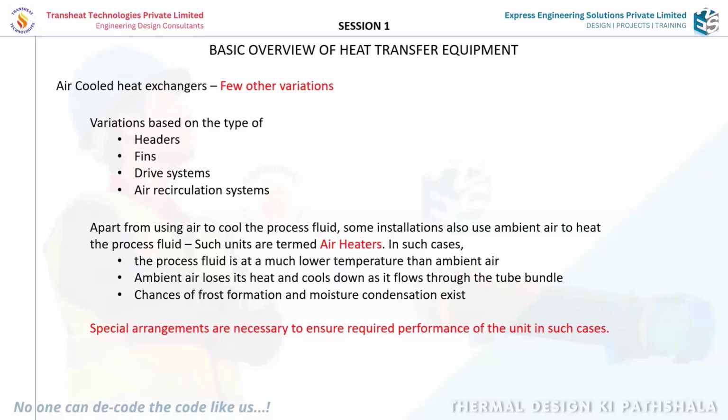So the chances of moisture condensation and frost formation on the finned surface become very high. So we need to see how we can address those issues. That is a totally different type of air heater which we design in some cases. The concept is the same, but you have to address these other issues like frost formation and moisture condensation.